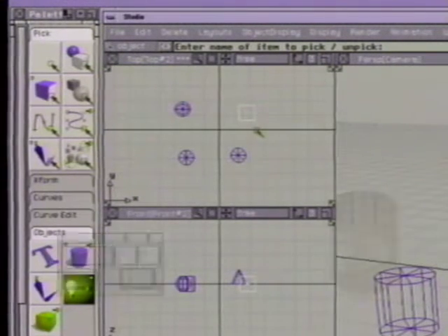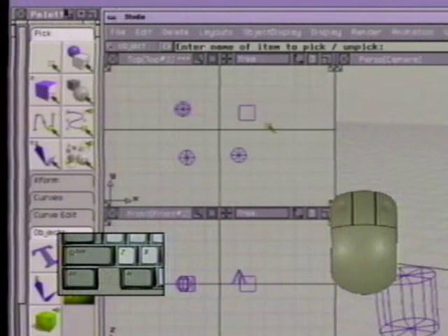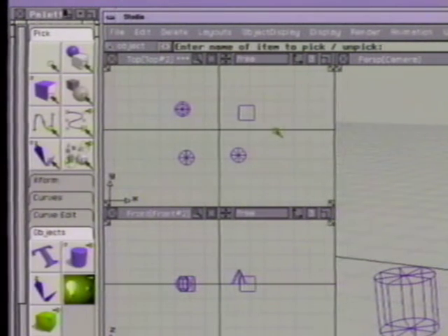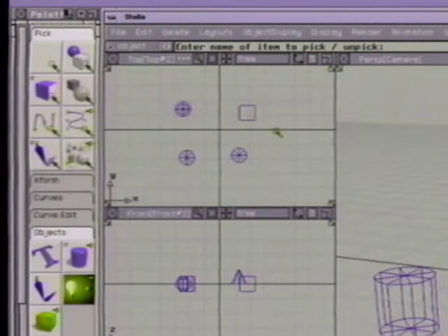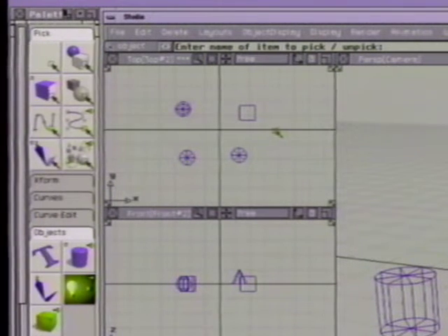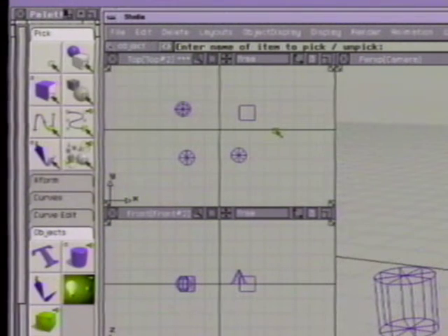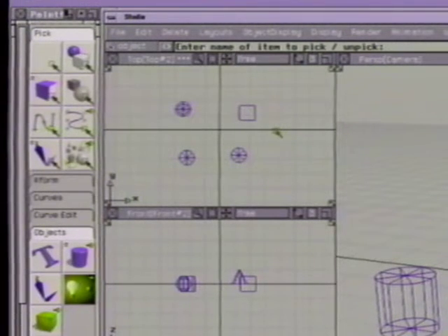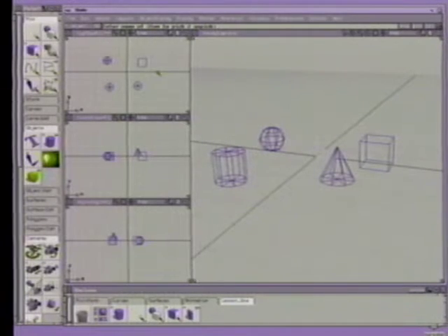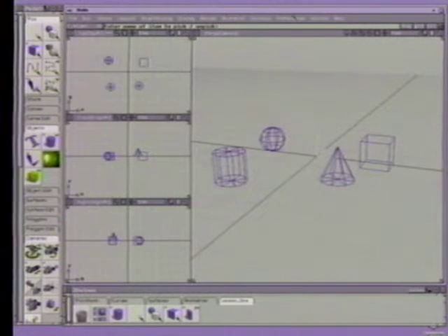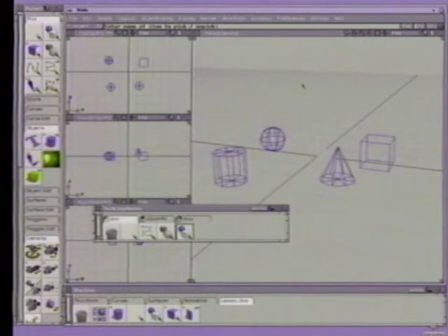Press the Control and Shift keys and click-drag quickly in an up direction and release the mouse button. A black line is drawn, but no marking menu appears. You have just used the Pick Nothing tool without actually seeing the tool in the workspace. Once you become familiar with the radial position of the marking menu tools, a quick click-drag gives you intuitive access to these functions. To edit the tools available on a particular marking menu, go to the Preferences menu and choose the Edit Marking Menus function.